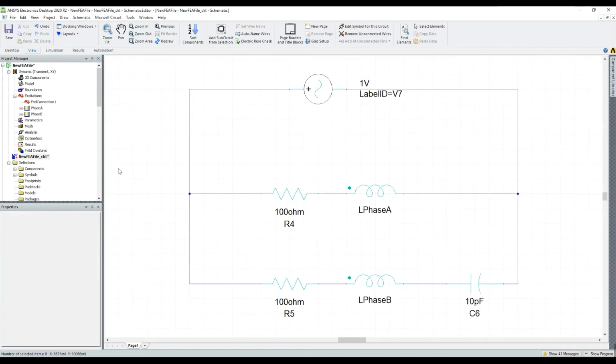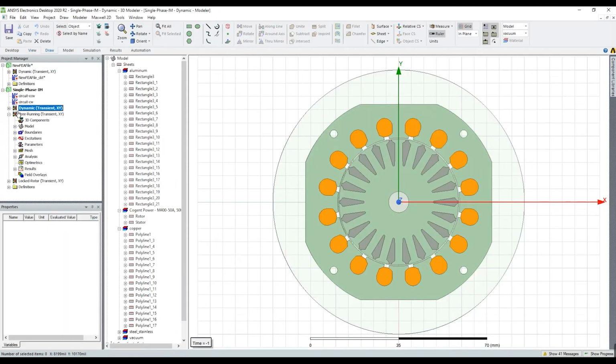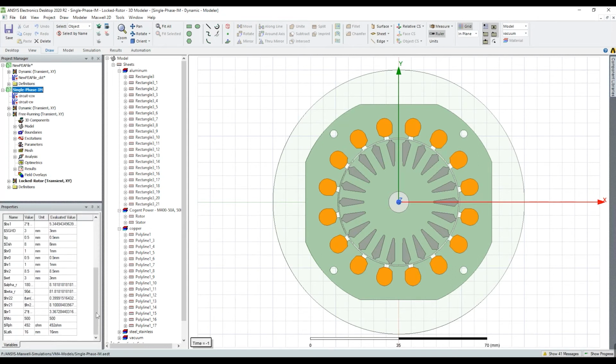And what is the value of resistance? Coil resistance, I calculated the value of coil resistance, and I measured it using the ohm meter. The value is 492. This is hot resistance, not cold resistance, because I also considered an operating temperature.